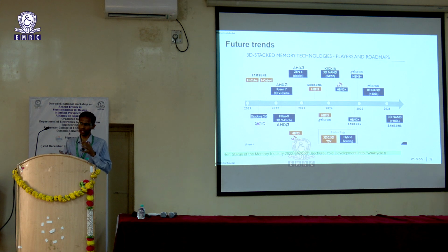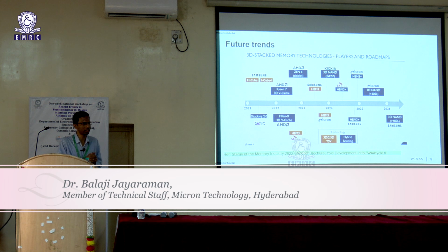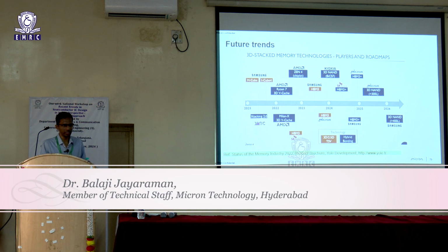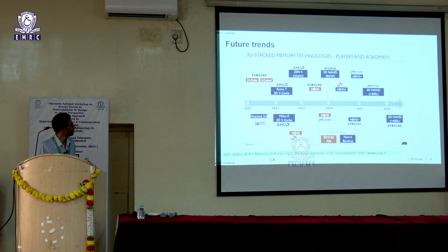When you talk about 3D NAND, you have NAND cells with 232 layers or 276 layers currently available in the market. And going forward, we might have 3D DRAM as well. So this is existing, and beyond 300 layers is something in pursuit. And then there are hybrid bonding and 3D or 2.5D TSV enabled approaches. When we talk about hybrid bonding, we are talking about having an interface die and a DRAM die as two separate entities which are hybrid bonded. And TSV, as I said, is a monolithic same die replicated multiple times, and they talk through TSVs.